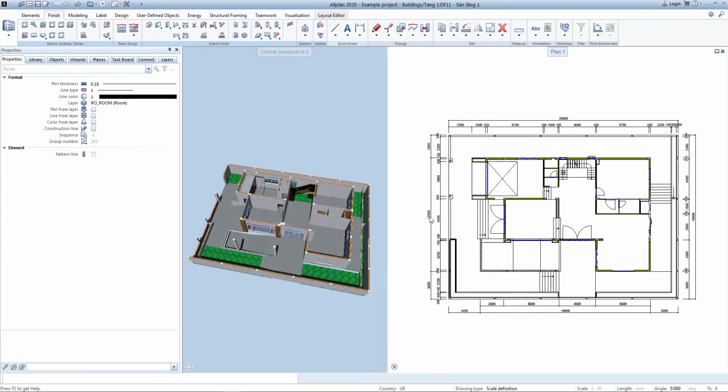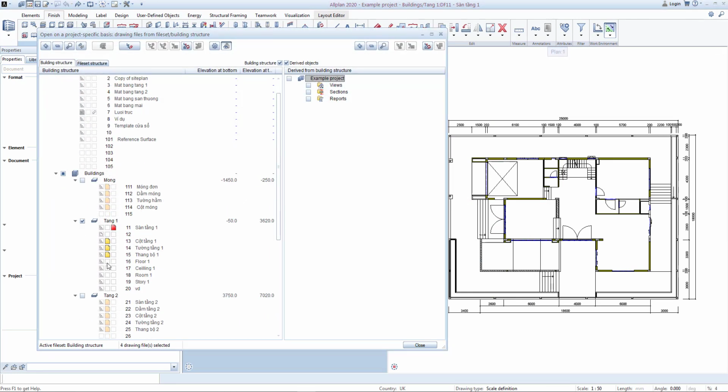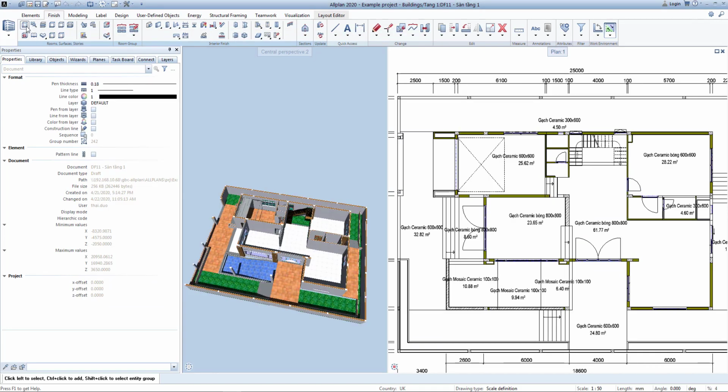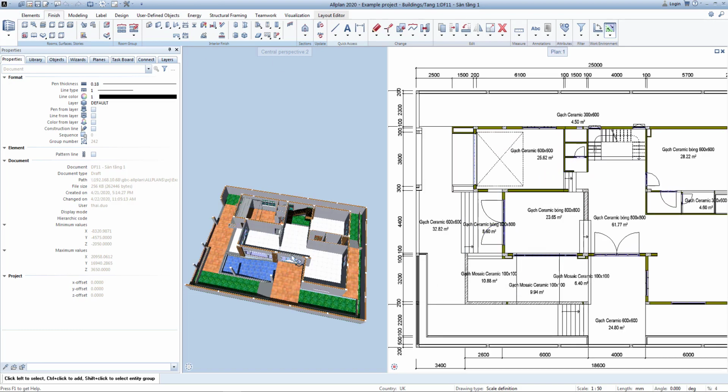In addition to the room tool, we can create separate finishes such as floor, ceiling, vertical covering, and baseboard. With these finishing layers, you can define details by the same named functions for the finished surface, like I created here. We will go to a file to create the rooms.